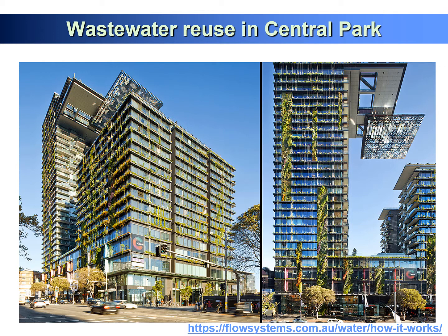We already discussed wastewater reuse in Block 2. In front of our university at UTS, we have Central Park, and underground we have a wastewater reuse plant. You already designed an anaerobic bioreactor, aerobic bioreactor, and membrane bioreactor. The membrane bioreactor is located in the basement of this building, and we have reverse osmosis for wastewater reuse. This reverse osmosis will be covered in this Block 3, which will give a better idea of how to remove all the contaminants to produce recycled quality wastewater.